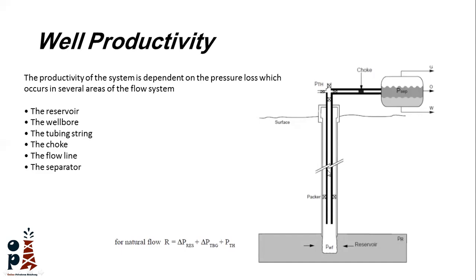Then the reservoir fluid is moving up across the completion, the tubing with its accessories, if it has some nipples or anything, until it reaches upward to the tubing head, the Christmas tree. And then it moves from the wellhead to the separators or whatever the production facilities through some flow lines and the choke if it's required. So as a petroleum engineer, I'm concerned with the pressure drop across this system because in this system I can optimize the maximum flow rate and the maximum revenue.